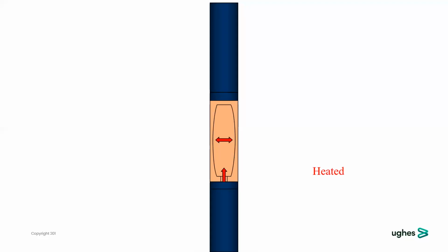That rubber element is expanded with the heat of oil during operation. So if you go on operation and the oil and fluid of the motor are heated up, that bag will expand in order to have a bigger volume to withstand the higher volume of the motor oil.